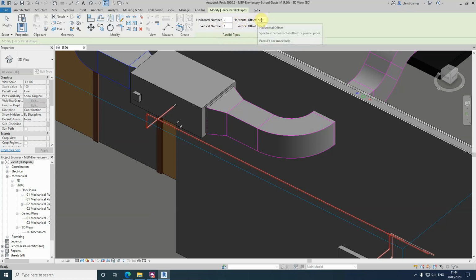And obviously we need to set our distance of how far we want the pipes to be apart from one another. Obviously horizontal, since that's all we're interested in, is 50. The vertical offset you can ignore, you can leave this whatever the default is, or we can change this to 0, because we're not really going to apply the vertical in this instance. That would come into it when we've got a figure higher than number 1 here.